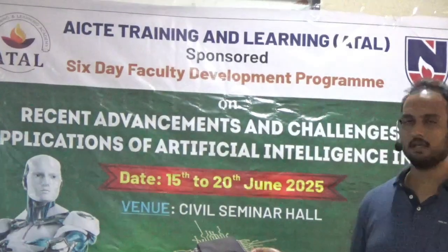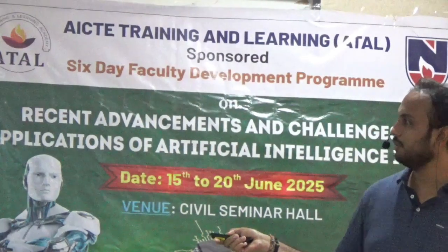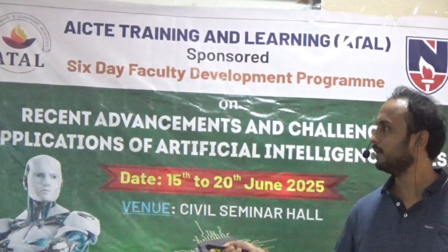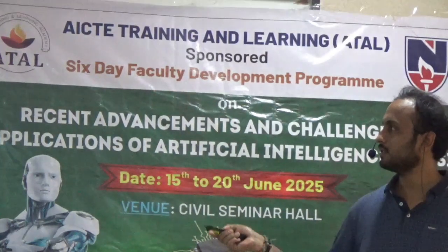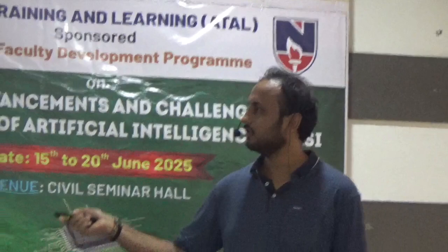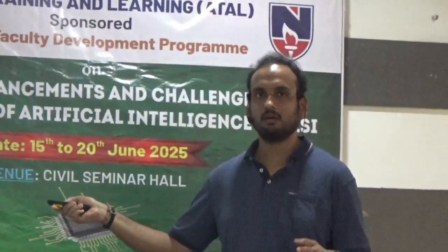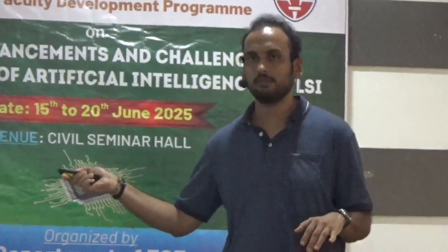So gm/ID is another parameter. When we talk about weak inversion, the overall gm you will get is very minimal, so it is very less. But when you go for gm/ID, it is best in weak inversion. In the strong inversion region, which is the square law region here, it is always somewhere minimal or in between. So you will get moderate gm/ID and gm.